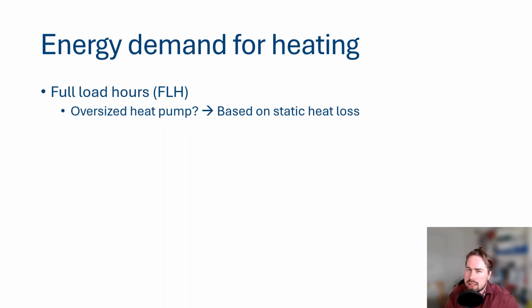So that's a really easy way, typically how it is done, but the problem is that if you oversize your heat pump, your energy demand will also be oversized. So if you have the same 7 kilowatts of static heat loss from before, and we install a heat pump of 8 kilowatts, assuming the same 1000 full load hours, it's 8000 kilowatt hours instead of 7000. So it's important to factor away the potential oversizing of the heat pump, and base this on the static heat loss instead of the size of the heat pump.